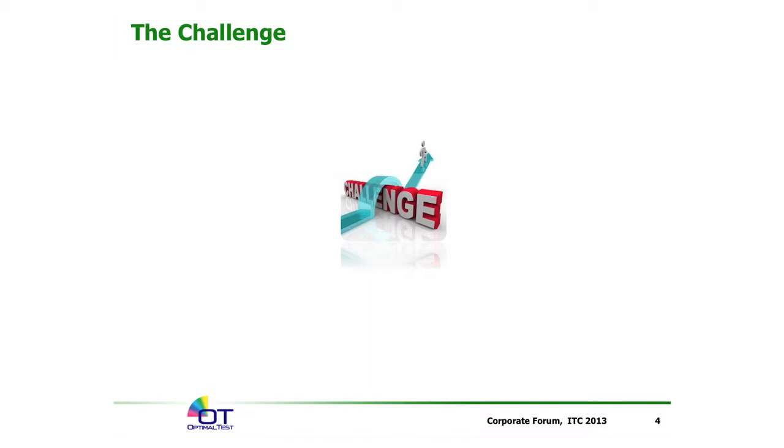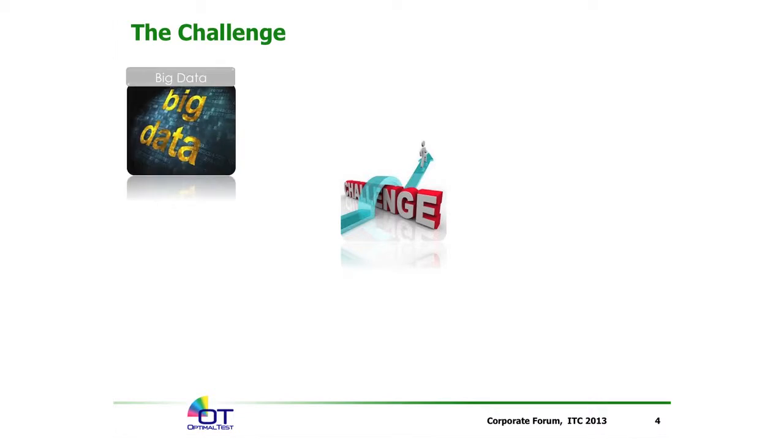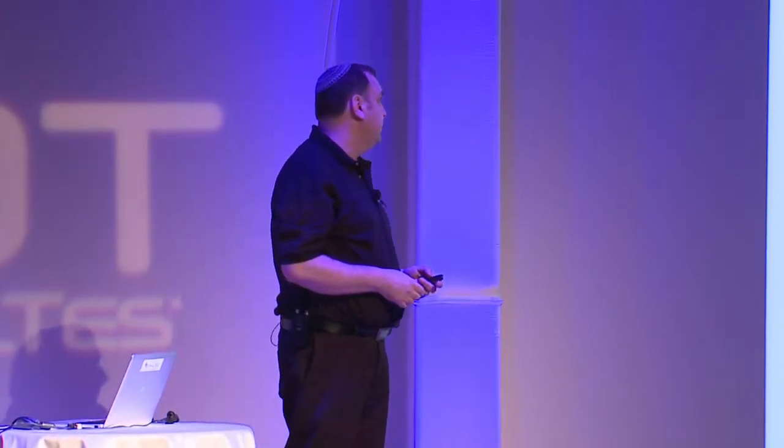So what is the challenge in performing escape prevention? There are actually several challenges. The first challenge is everything that comes under the umbrella of what's becoming more and more widely known in the database world today as big data. The complexity of your parts is increasing over time. A typical chip now may have as many as 2, 3, 4, 5,000 parametric tests, possibly even more than that, being collected at each operation. The speed at which you're collecting that data is growing over time because the testers are more powerful, the workstations are more powerful, and so on.